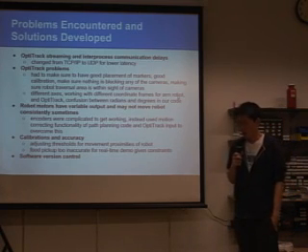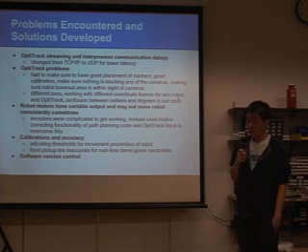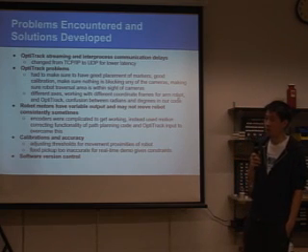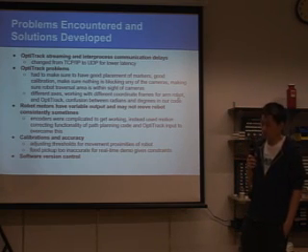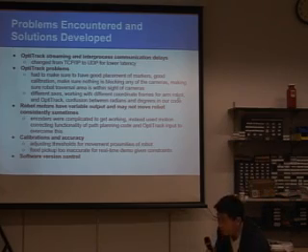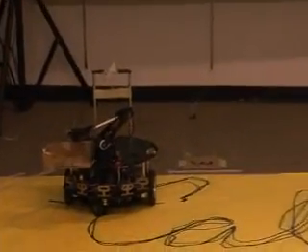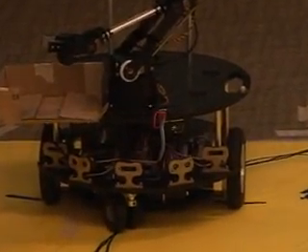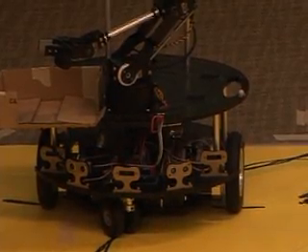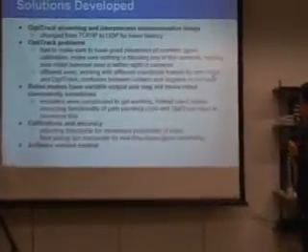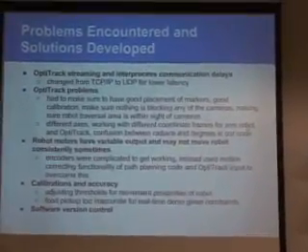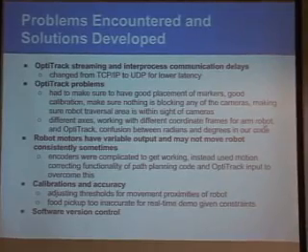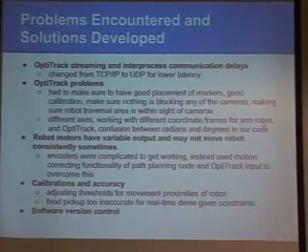The robot motors on the Parallax Eddy board, we initially wanted to use encoders because the forward motion was not entirely reliable, especially with the two smaller wheels that control the turns, it sometimes just gets in the way of the forward motion in specific situations. So we just needed to ramp up the power going to the motors for more reliable movement, and we did not get the encoders to work. So we just relied on the path planning code to correct for any errors that the wheels would give us.